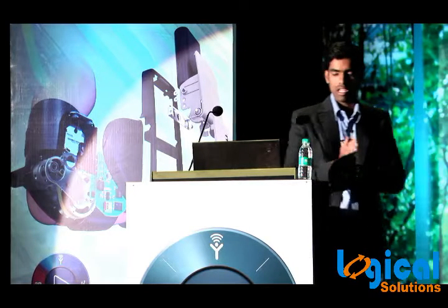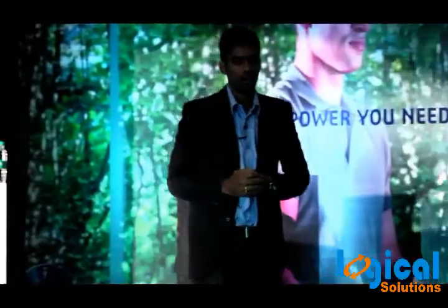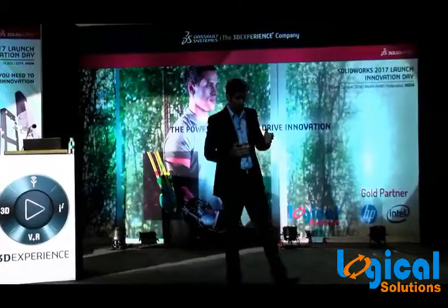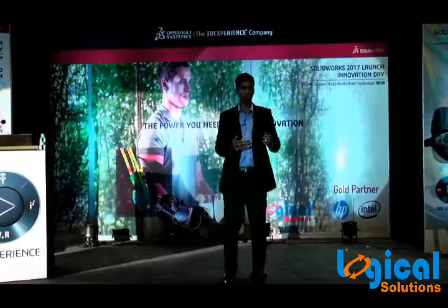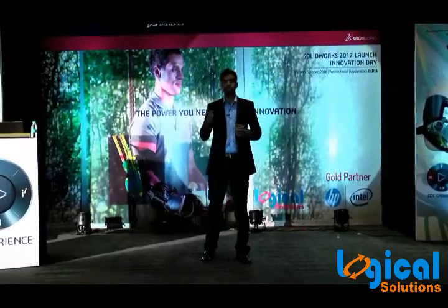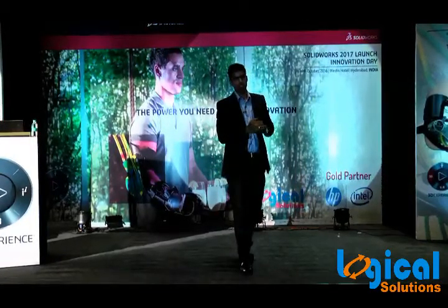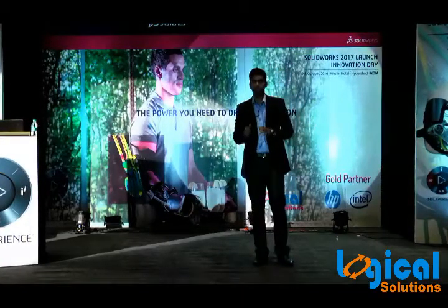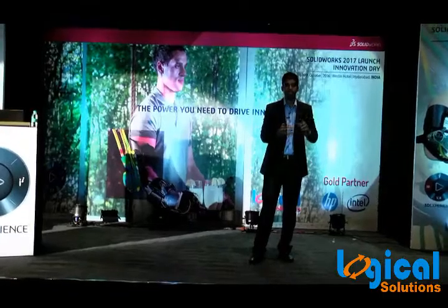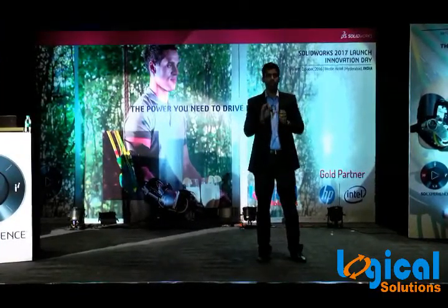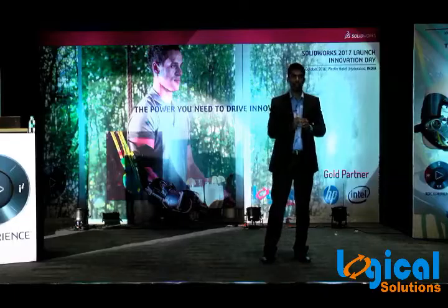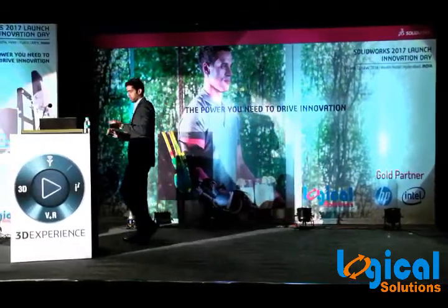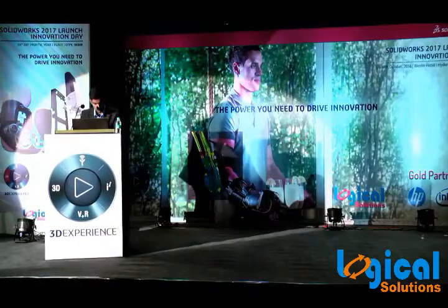The next enhancement is about sketching. As we all know, SolidWorks is a wonderful tool for sketching, right? It is very user friendly, you can make a sketch, but previously you could not move the sketch. Now there is a latest update in SolidWorks 2017: if it is a closed contour, it will be highlighted with a different color, and by selecting a closed contour you can drag and drop the sketch wherever you want. So let us see a live example of this.